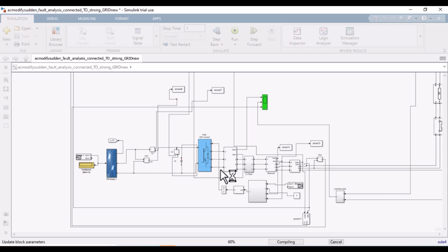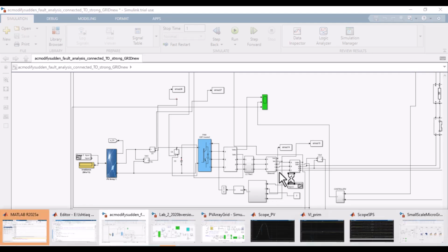The solar PV array, actually here is an inverter connected. These are the control systems, PID controller, and the gate pulses are also regulated. It's also taking the feedback from the main grid and redesigning the regulated signal for generating the gate pulses. So it's a very heavy loaded model. The LC filters are also necessary if you are using an inverter connected to the PV array and for the other microgrids. If we couldn't use the LC filter, then our waveform is not accurate.